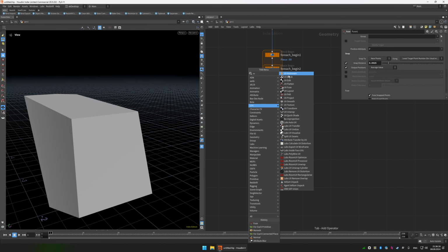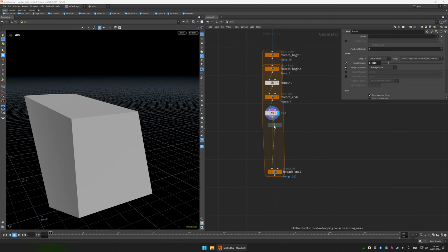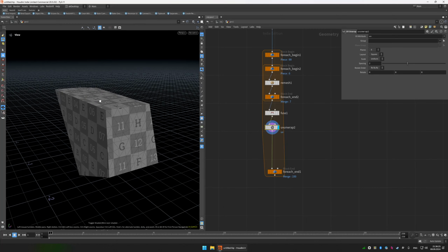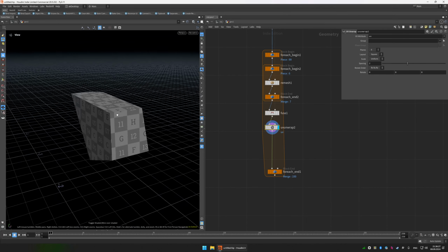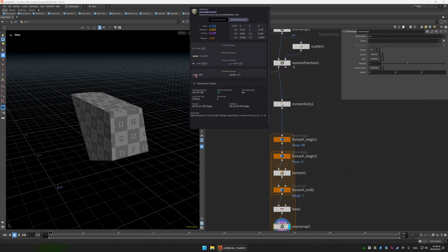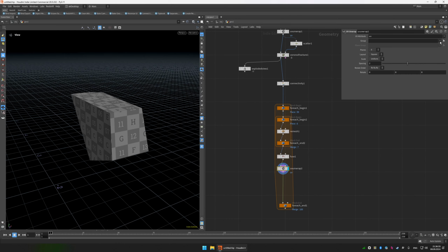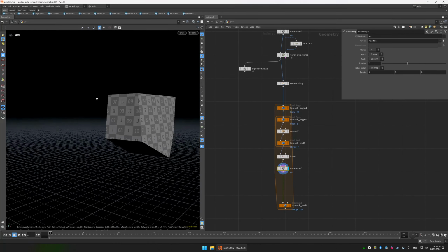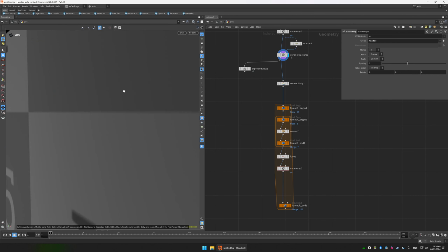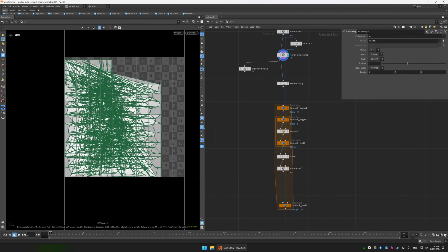And then also what I did was I generated the UVs for the insides, so for those pieces, and of course our Voronoi fracture gives us the inside group here, so we can use this group to calculate UVs just on the insides, because we don't want to mess those UVs.